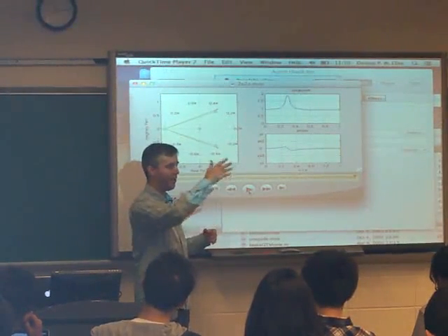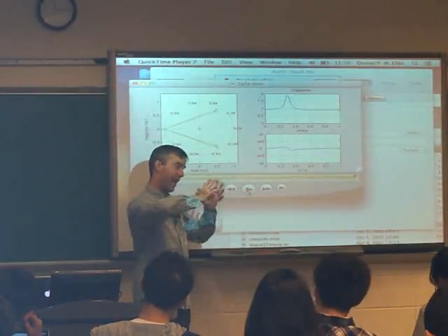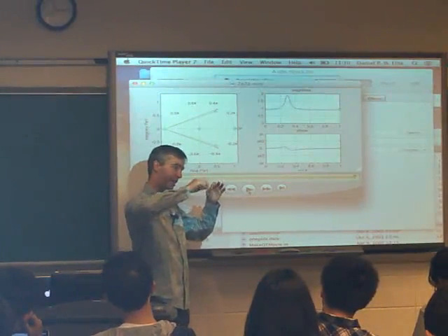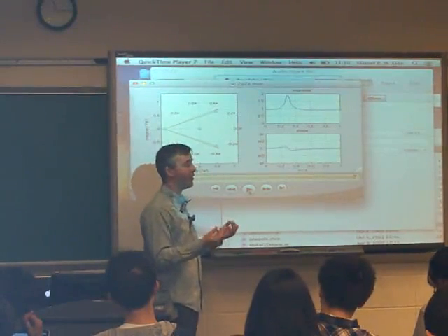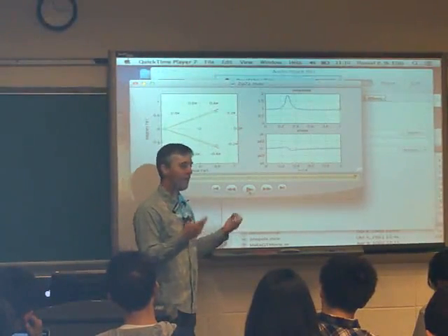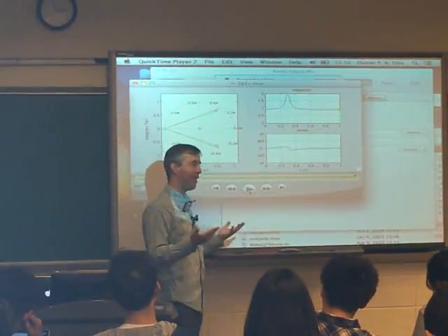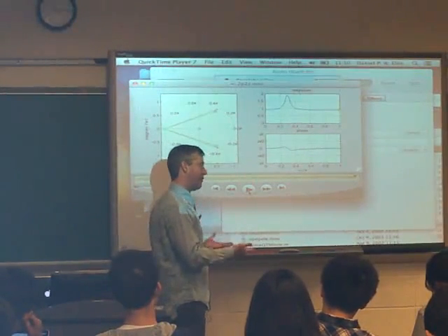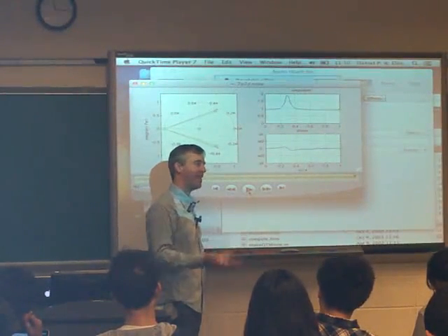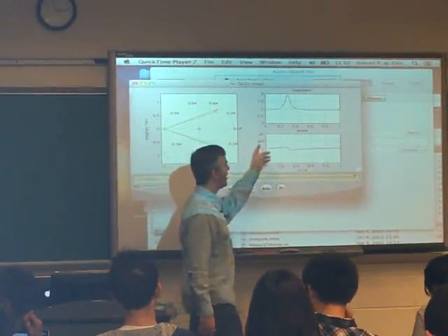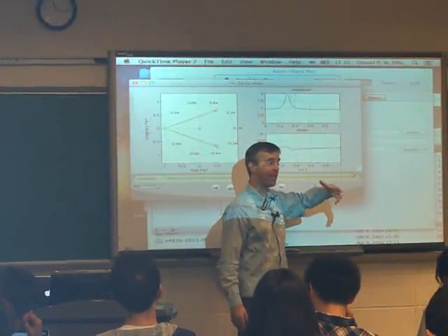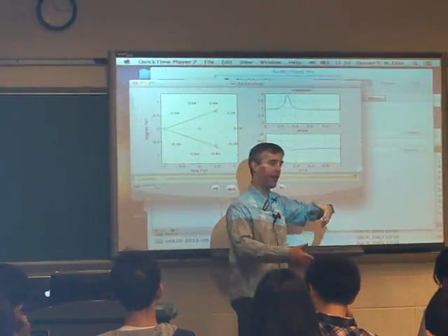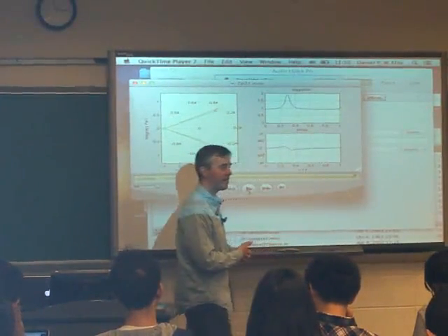The points have this aliasing effect where they're equivalent to changing by a lower step every sample, and so they become aliases. They don't look like the frequencies you want them to be, and they become ambiguous. So pi radians per sample is the Nyquist limit, the largest step we can take before we start looking like something else.